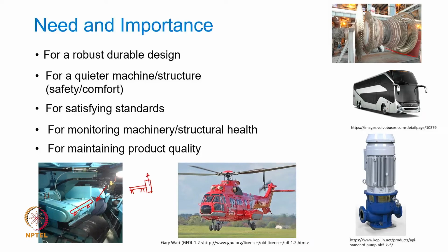A rotating system can vibrate under the action of residual unbalance or even cutting forces. Now, if this grinding wheel starts vibrating with micron level vibrations, and if your cutting process is removing micron level material, then the vibration itself may generate additional material removal, and the accuracy of the parts produced can get seriously compromised. So, ensuring product quality will also need a high level of vibration reduction and almost vibration free equipment.